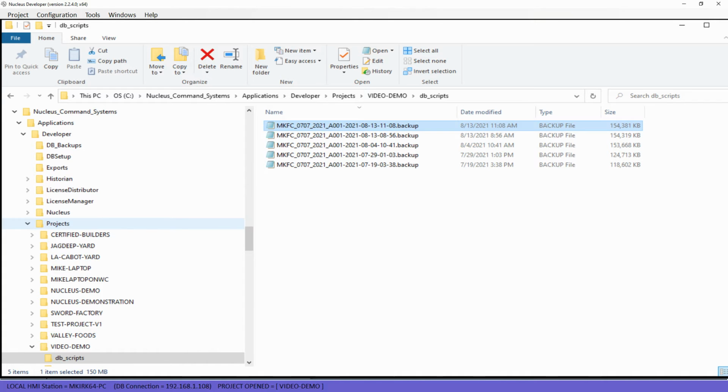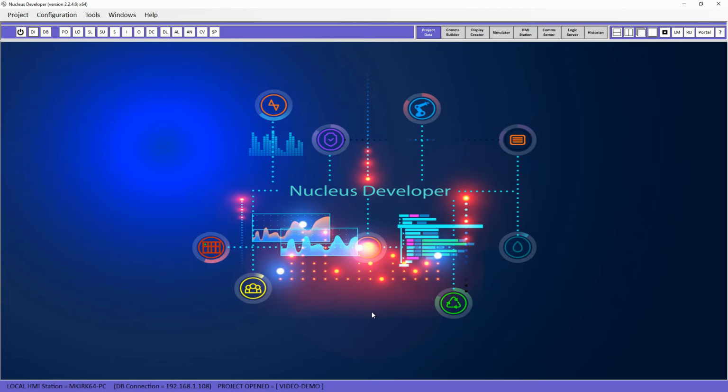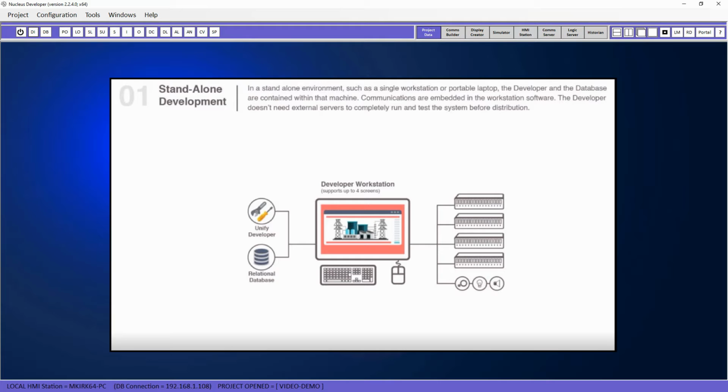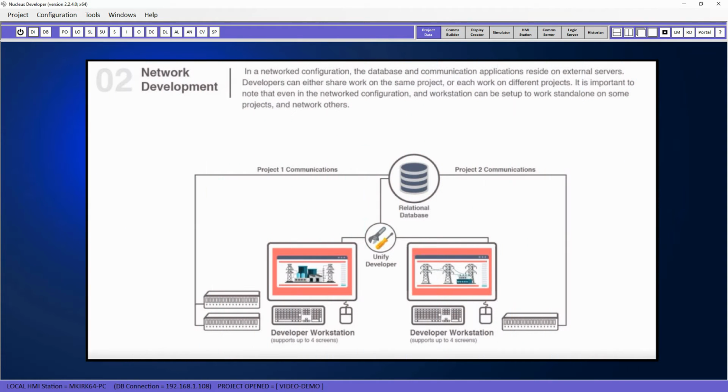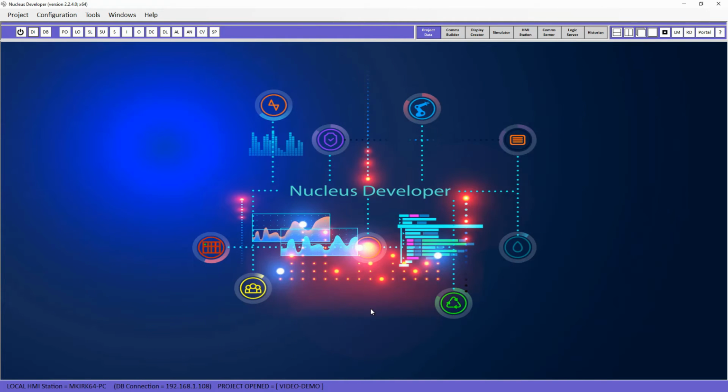Backup and restore also play an important part in copying project databases from one computer to another. The following diagram shows a typical local host configuration where the Postgres cluster is running on a desktop machine or a laptop containing the Postgres cluster. The next diagram shows how the developer application is on multiple workstations where each integrator shares the project databases. Obviously, you can have many different projects on this shared cluster. The only limitation is that two developers cannot work on the same project simultaneously.